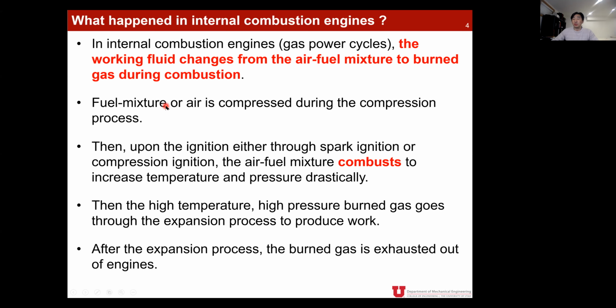And this fuel mixture or pure air, depending on your engine, is compressed during the compression process. Then right after the compression process, fuel is sprayed onto highly pressurized air. Then either by using spark ignition with a spark plug, or a spontaneous compression ignition process, your air-fuel mixture now combusts to increase its temperature and also pressure drastically.